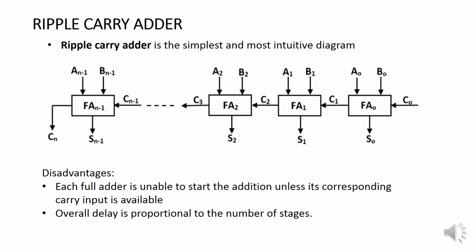When we perform an addition by hand, starting from the less significant column, we add the digits of each column. As a result, a carry is originated. In the case of binary numbers, this carry can be 0 or 1. When the carry is 1, this carry is added to the next column to obtain the result, and this process continues successively as long as there is a carry. So, from the least significant digit to the most significant digit, the carry is moving stage by stage.